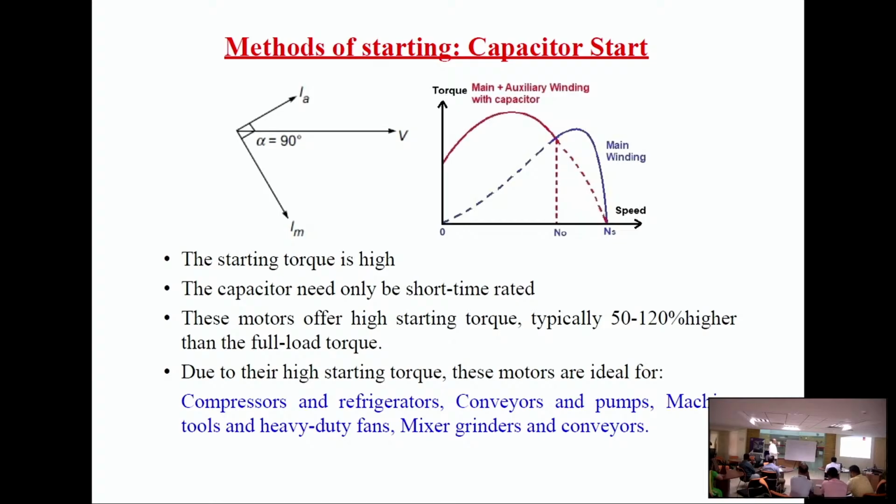And due to the high starting torque, for those applications against heavy load when you start, you can use this motor, like compressors, refrigerators, conveyors, pumps, machines. So this is capacitor start, only at starting.